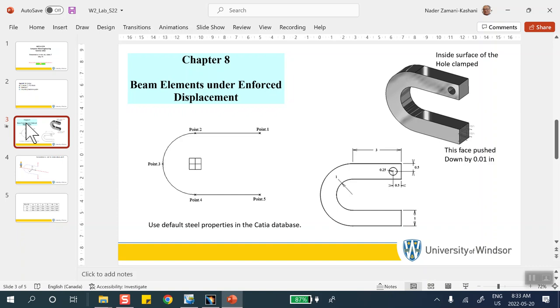Of course, even there you can set those things, but Catia won't let you do that, bottom line. Now, that does not mean that beam elements are useless, okay? In many situations, you may not be interested in the stress in the beam, but you want to make sure that beams support other things, such as this safety glass. What we may be interested in is the shield itself, and these are supports. We just have to make sure that they're reinforced properly, etc. Hopefully, this was designed so that it carries that weight. So we are not necessarily interested in the stresses in this, but we are interested in the stresses in this or the bottom, the legs, etc.